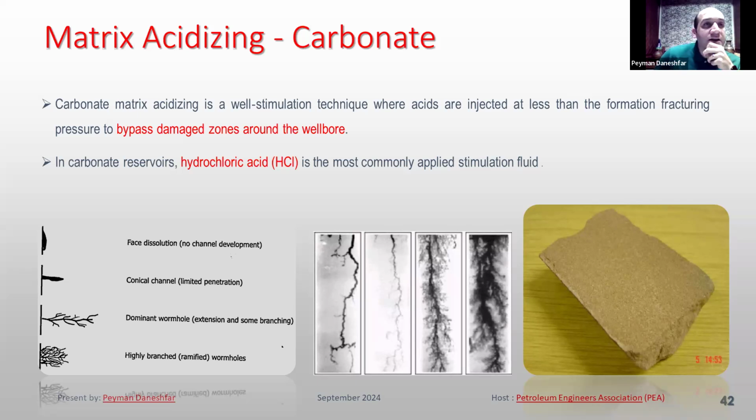We increase our HCl acid more, and you can see that a conical channel will occur. With limited penetration, more volume gives more penetration, but think about the volume, think about the reaction time, think about which additive should be added to this acid to get a good result.